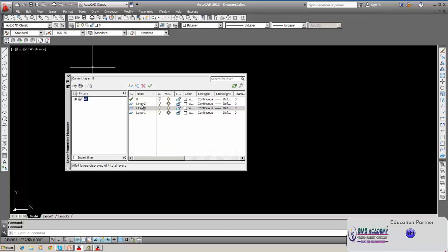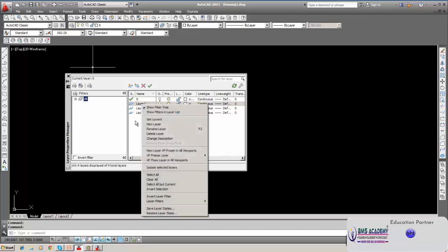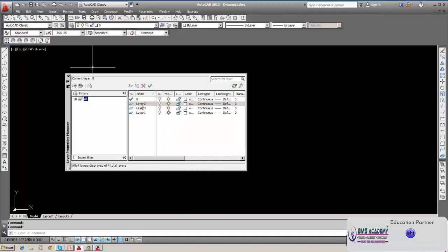See, these layers can be named also. You click on this and click it a little bit. So it is here. You can name it. Say I want to name it A. And the second layer, you click on this, click here. It gives provision to change the name, B. Click on this. See. So we have created 3 layers.